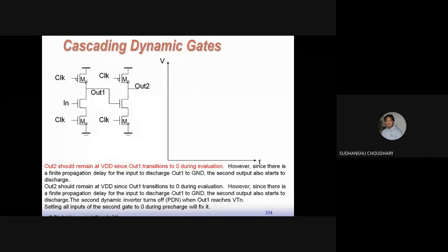So in the previous lecture, we had seen some combinational logic designs based on static CMOS inverters, and then some other non-conventional designs, for example, the pseudo NMOS and the depletion load NMOS based devices. And then we also saw the effect of multiple threshold drops which was happening when cascading the pass transistor based logic designs. And we then also talked about the dynamic gates.